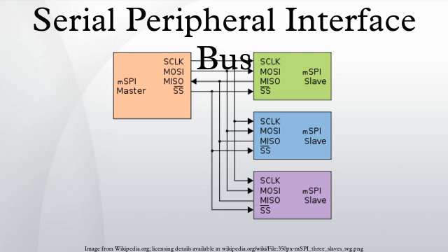That is, CPHA equals 0 means sample on the leading clock edge, while CPHA equals 1 means sample on the trailing clock edge, regardless of whether that clock edge is rising or falling. Note that with CPHA equals 0, the data must be stable for a half cycle before the first clock cycle. The MOSI and MISO signals are usually stable for the half cycle until the next clock transition.